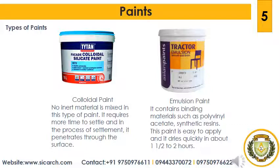It contains binding materials such as polyvinyl acetate and synthetic resins. This paint is easy to apply and it dries quickly, in about 1.5 to 2 hours. The color of the paint is retained for a long period, and the surface of the paint is tough and can be cleaned by washing with water. There is absence of odor and the paint possesses excellent alkali resistance.